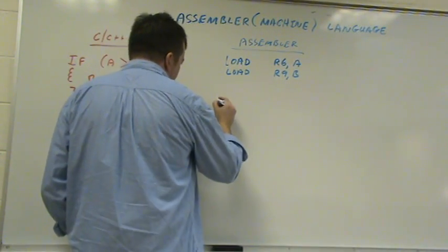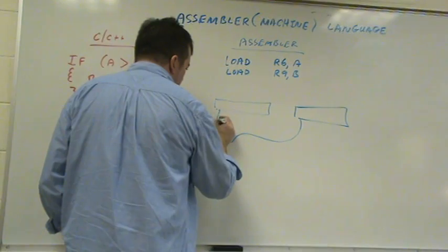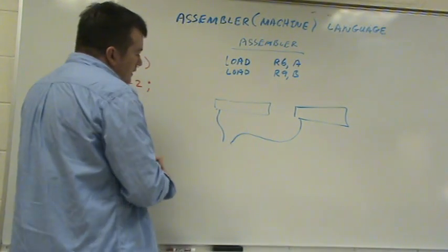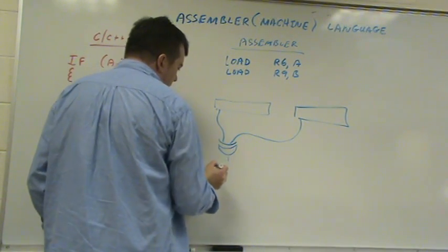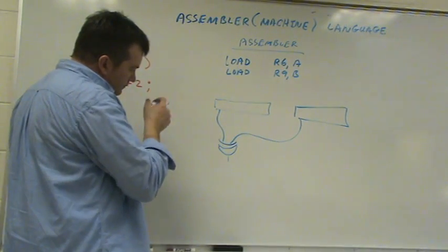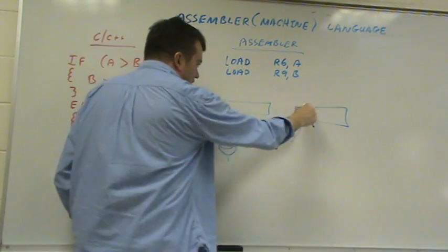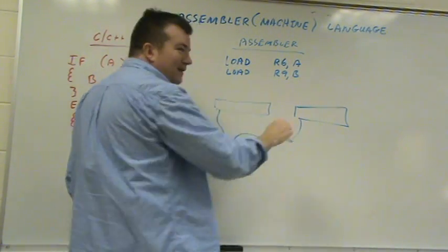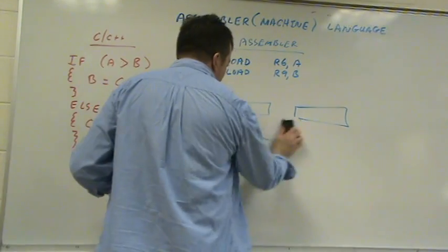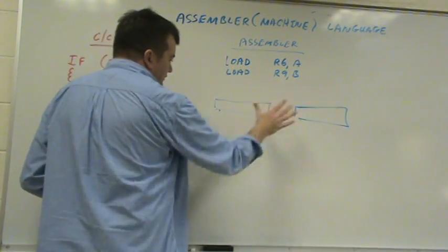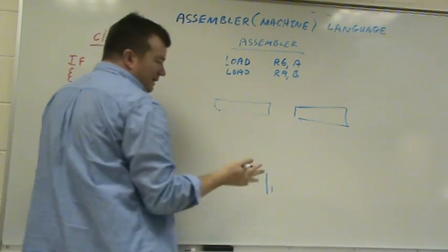We would have to take the two inputs and say, this number and this number, if they don't equal each other, we could use an exclusive OR. Well, okay, so we'd have to come up with something. If they did equal each other, then we want electricity to go through to the next two, bring those two out, and if they equal each other, go back. So we could kind of do a rippling. We could eventually come up with a piece of hardware that takes as input two registers, and has one output that's a 1 if this one's higher than this one, and a 0 otherwise.